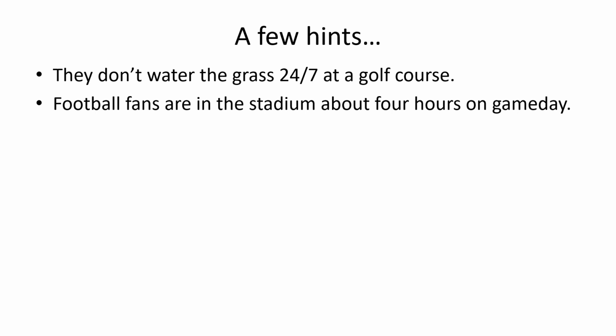And for example, for a football stadium, we don't want to figure out how much water is needed in a day and then spread it out over a 24-hour period, because during a football game, the peak demand comes maybe during the halftime of the football event. So you'd have to be thinking, based on how many people are there, how many toilets might they have? How many drinking fountains might they have? How many of them are flushing at the same time? How much water is used during the 25 minutes or whatever, however long a halftime is.